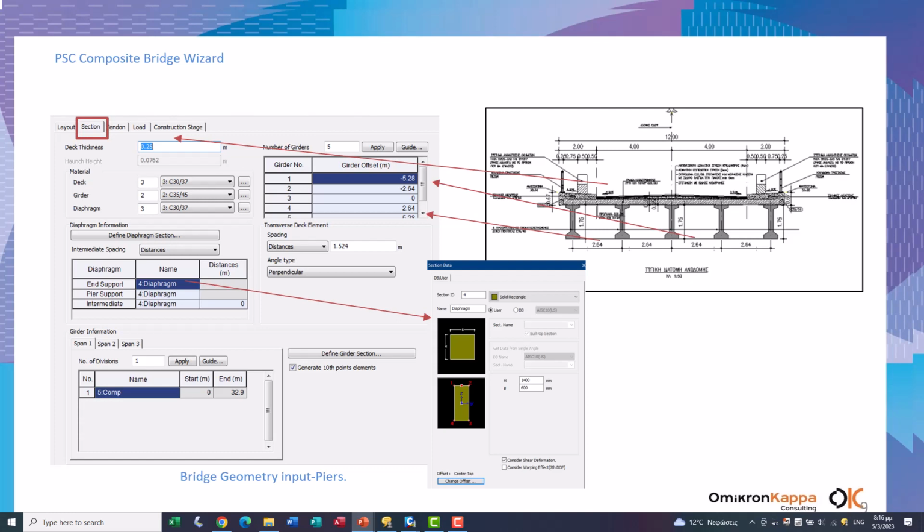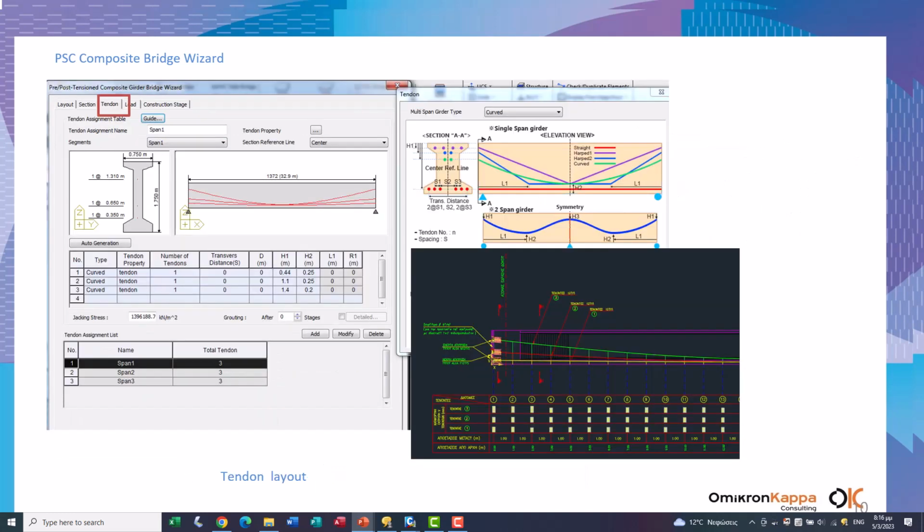And then we go to the tendon layout, which provides us the tendon arrangement and geometry of each tendon, which have 12 strands. Here we provide the geometry of the strand. We have used 3 tendons, also by the help of a sketch that Midas Civil has, and in table format